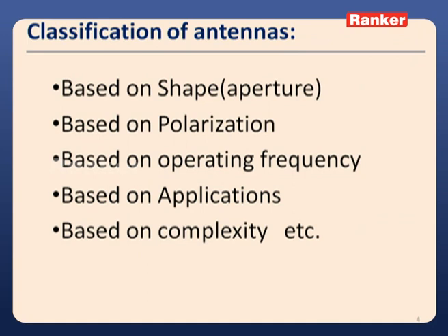Now we will observe the different classifications of antennas. Nowadays we observe different antennas for different applications. For TV reception, in every home you observe a simple antenna with a parabolic or hyperbolic reflector, also called a dish antenna. In the olden days, for TV reception we used an array called the Yagi-Uda array, or Yagi antenna. In mobile phone applications we may have a simple patch antenna. For optical communications or satellite communication applications, you may have a spiral antenna or a helical antenna. Like that, for different applications, different antennas will be there.